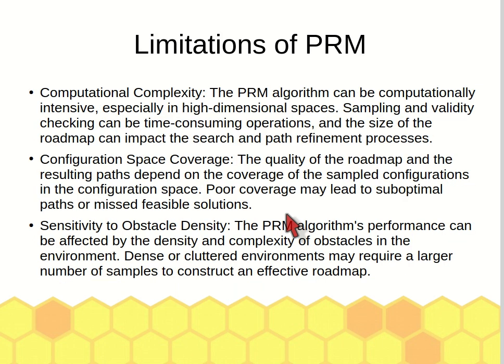Limitation of PRM: computational complexity is quite high, especially when it involves high dimensional space. The quality of the roadmap can depend on the coverage, and it is sensitive to the density of the obstacles.